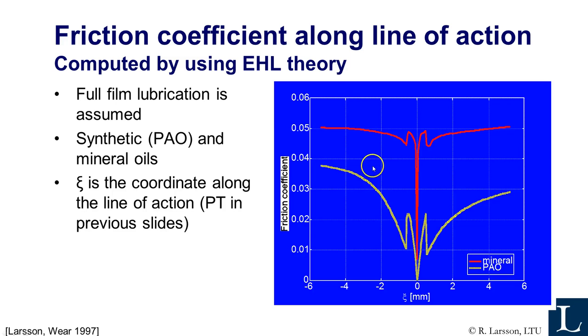parameters. So this can illustrate that if you select lubricants with what we call limiting shear strength properties which are good and beneficial, such as for this synthetic oil, you can reduce the friction pretty much in the contact. And the viscosity doesn't really play a role here. It's more the limiting shear strength, which we discussed in the elastohydrodynamic lectures.